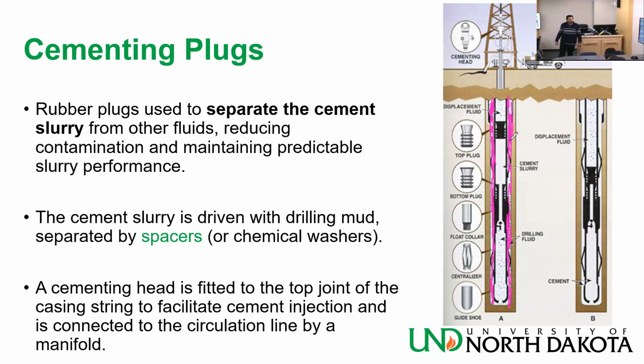I thought you remove them after. No. A centralizer is very, very cheap. It's used to stay there. Some of the centralizers you can even move with your hands. But yeah, this is where you want the cement to go, and this is your goal.